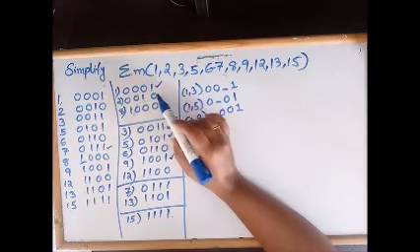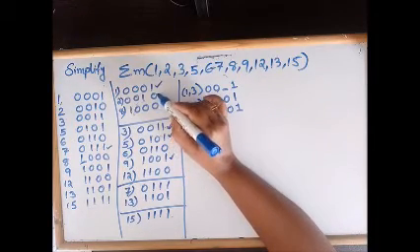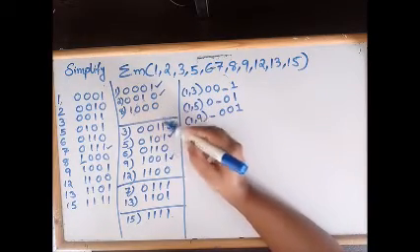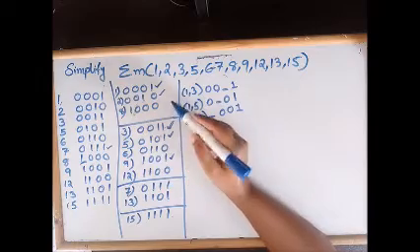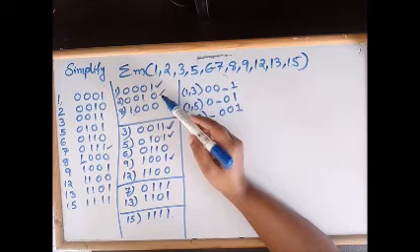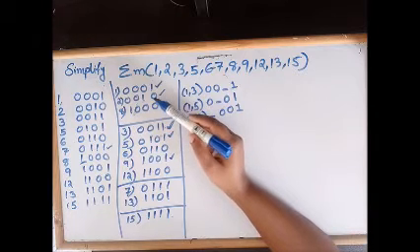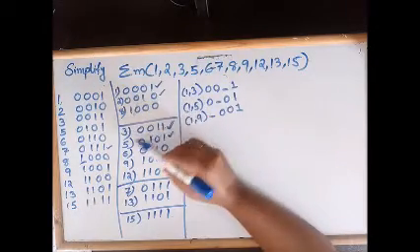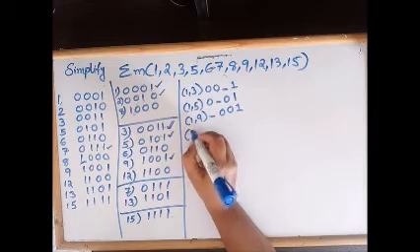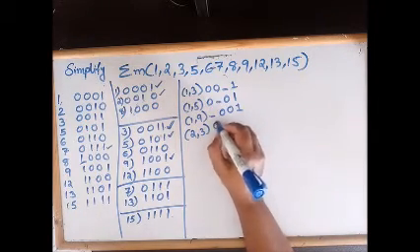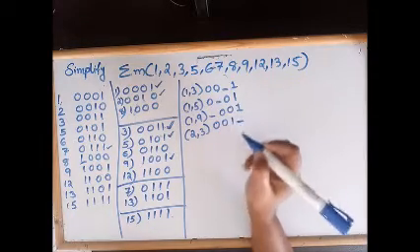So we can go for the next element, that is we can take 2 from the first group and again search for the other terms in the second group. First possibility, 2 and 3. When you consider 2 and 3, is it possible to combine? What about the number of bit changes? One bit change. So we can combine 2 and 3, that is only the LSB changes, so we can write 0 0 1 dash.